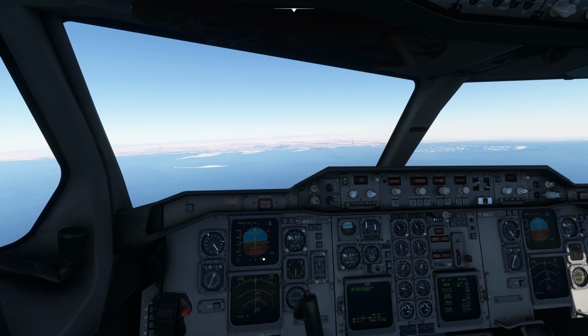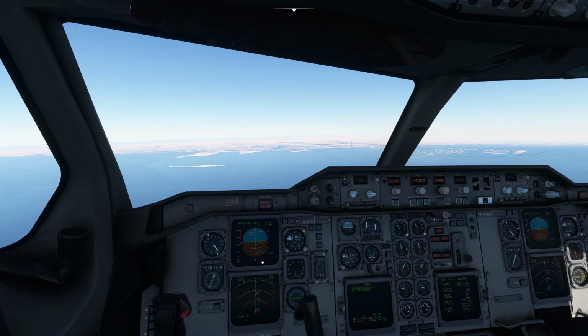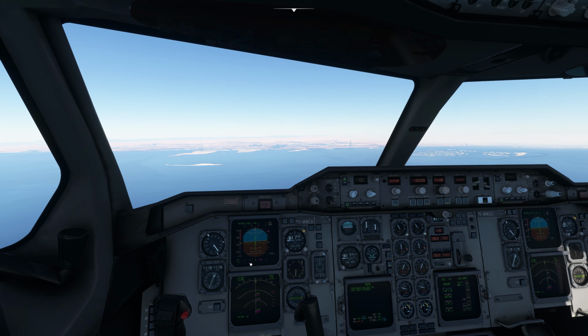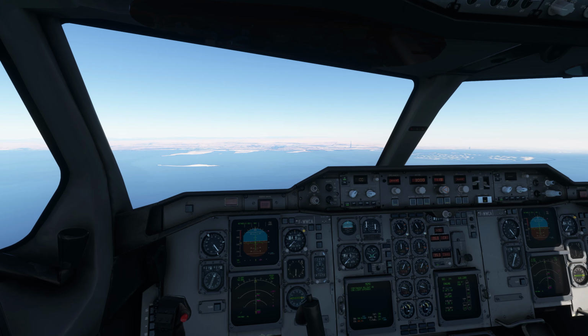Right now you can see the lateral alignment is not there, it's off. We are more towards the left side, but as soon as I press this button, land, in order to follow the glide path, the glide slope, this plane will align itself with the runway automatically. So this diamond will come in the middle. You will see some adjustments, but right now if I just proceed on this course, I will not be landing on 12 right, rather I'm going towards 12 left.